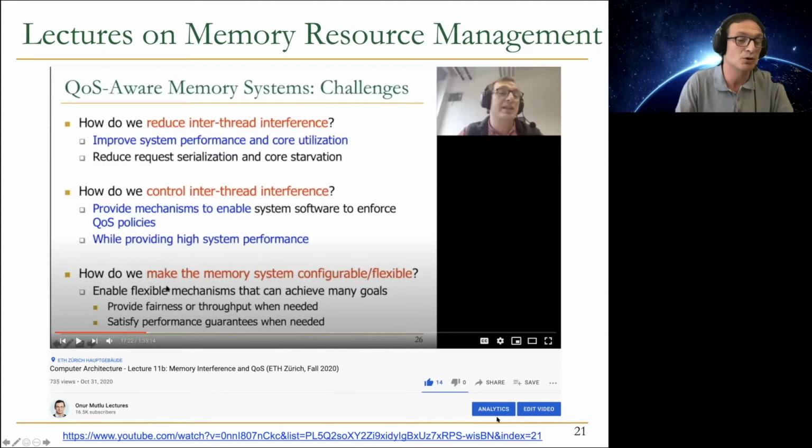And that certainly provides some sort of quality of service, but it's very hard to do that at all levels of the memory hierarchy. In the DRAM system, for example, it's very hard to partition the DRAM system such that each thread or each hardware context gets enough memory bandwidth, because today's systems are usually memory bandwidth limited, as we discussed, and we discussed the reasons for it also when we talked about the memory hierarchy, because you need to go off chip. And off chip, you have limited bandwidth, because you don't have enough pins, because you're limited by cost of pins and the cost of the system.